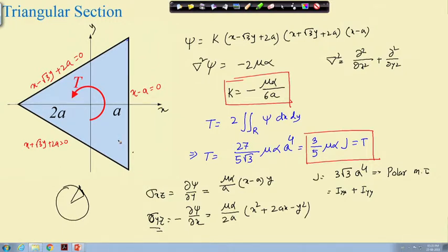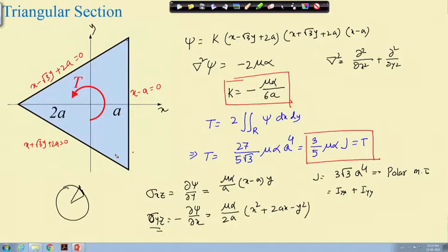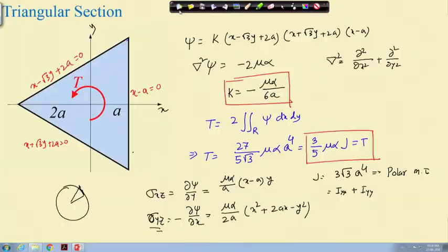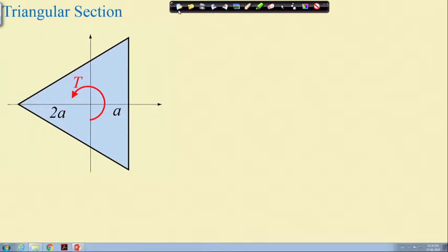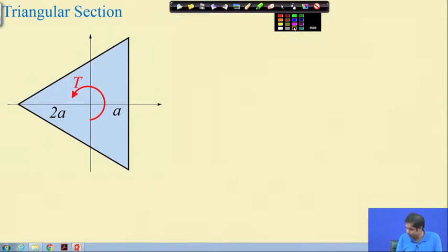Now, since it is symmetric with respect to the longitudinal axis, on all these surfaces the torsion stress will be the same. If it is the same, then naturally finding the stress on this surface will be easier, we can just substitute x is equal to a. Finding the shear stress due to torsion on this surface is enough, because on the other surfaces the corresponding stresses will be the same because of symmetry. If you do that exercise, I will just write the final component of the stress. The stress will be tau max.